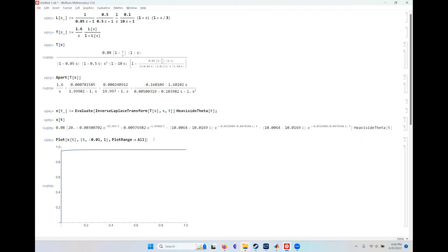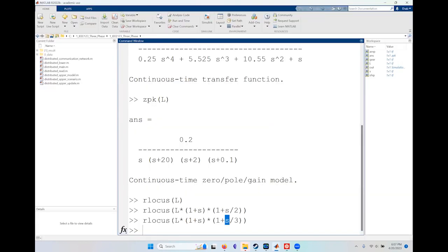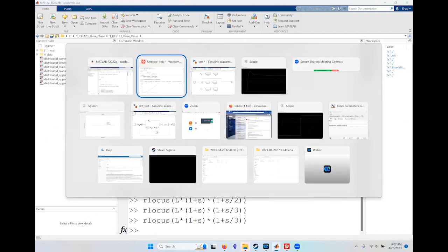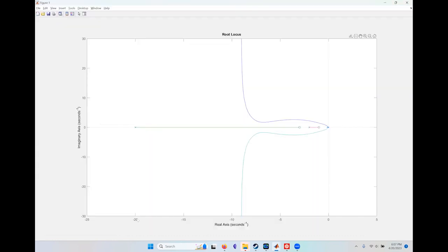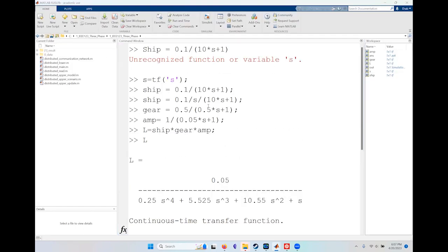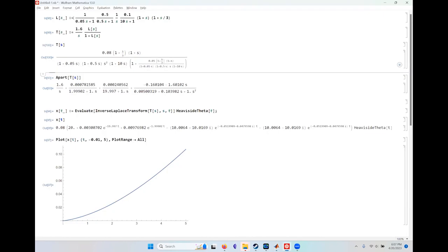And if I plot it in our simulation, let me do the root locus again. We looked at the root locus and we said we wanted to go all the way to a gain of 1960. So this is where we should be. If I don't put any gain, I'd be here, close to this place. So here I have to make the gain 1960. So it's not just 2 zeros, also the gain is 1960. Right?